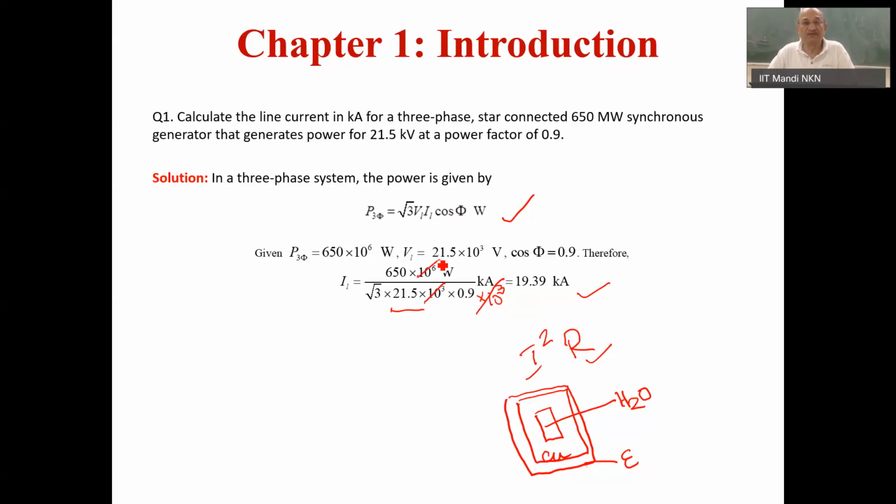And what would happen in those air pockets? Can you imagine? Air pockets are the weak points in the solid dielectric. And partial breakdown phenomenon takes place there. So if you increase the voltage, the intensity of partial breakdown in the air pockets formed in the taped insulation would increase, and it may not provide you the life you desire. So, especially in the case of generators, there is a limitation of the maximum voltage at which the power is generated.